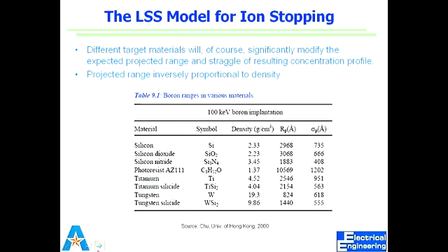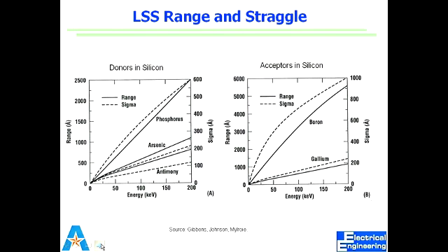Do you want to do an oxide mask or can you just. So this is entirely different parameters than diffusion when you're doing ion implantation. Right? So this is now for donors and acceptors, phosphorus, arsenic, and boron and gallium. Same concept, now a little more precise data. So this is all known. Now for you to look up, when you're defining your ion implantation recipe, you don't have to calculate all those things either.